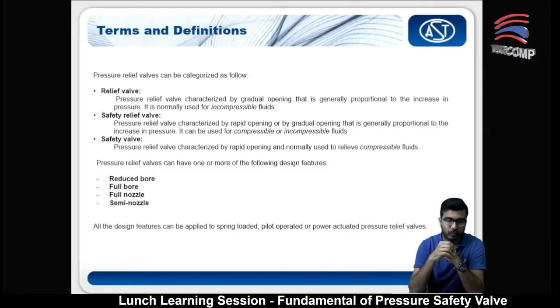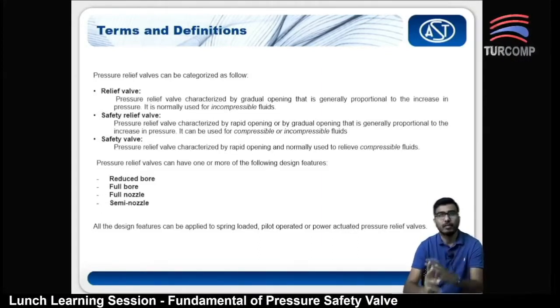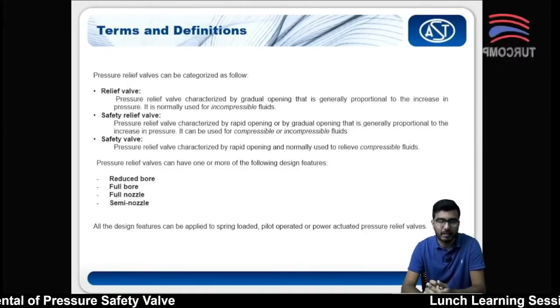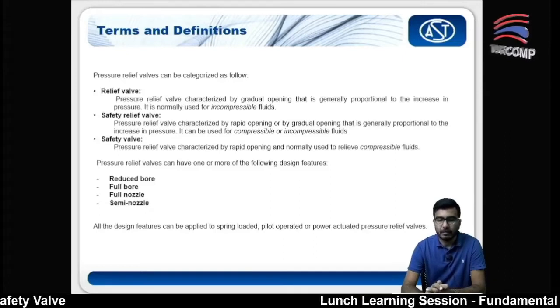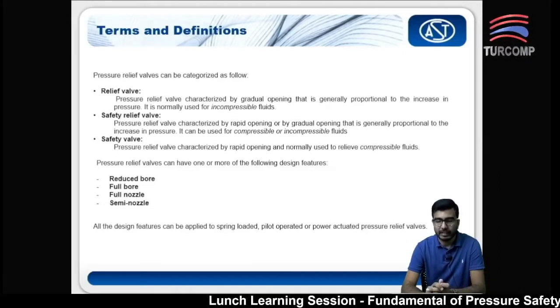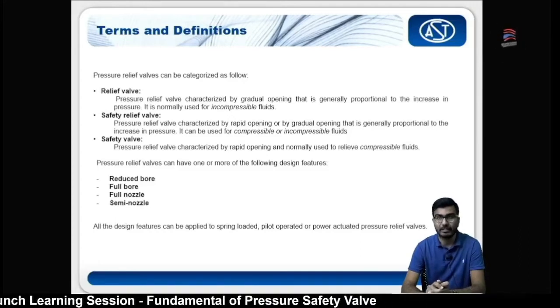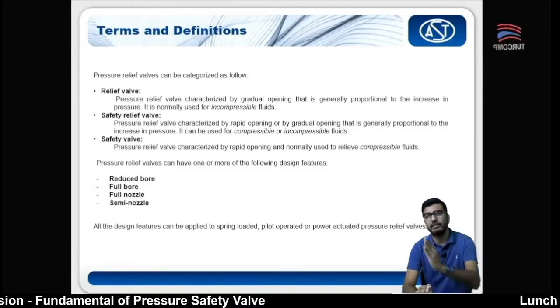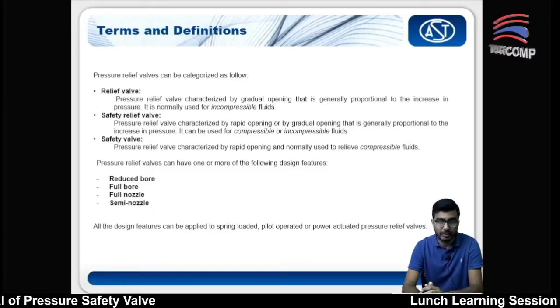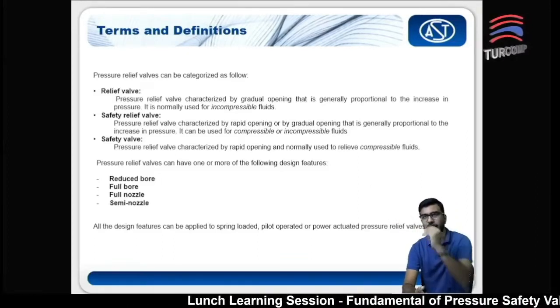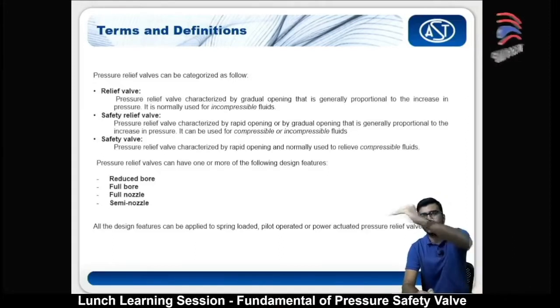Whereas safety relief valves are pressure relief devices which are characterized by rapid opening or by gradual opening that is generally proportional to the increase in pressure. Meaning this one you will have a slightly straighter graph. Because it's a function of safety, you need to relieve fast, so it will have a straight line, unlike the relief valve just now, which has a curve.